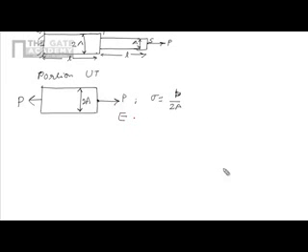E is given as E, which means that we assume that Young's modulus is E. So the strain is sigma upon E. That is nothing but P upon 2AE. Now the length of this portion is L.